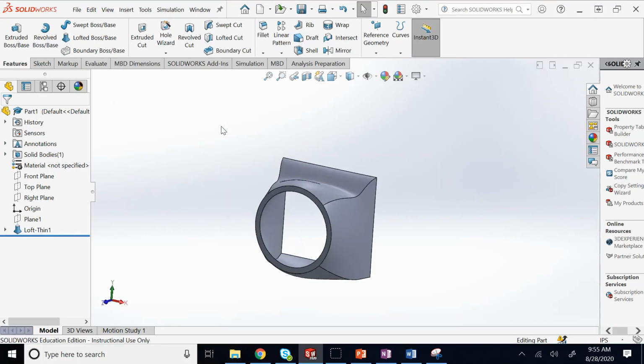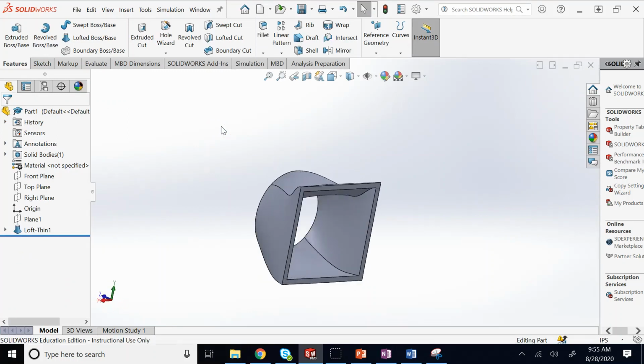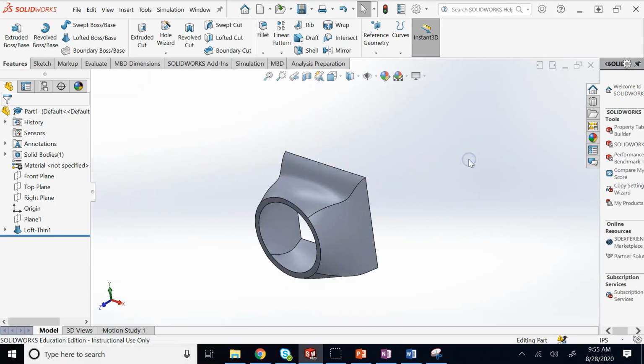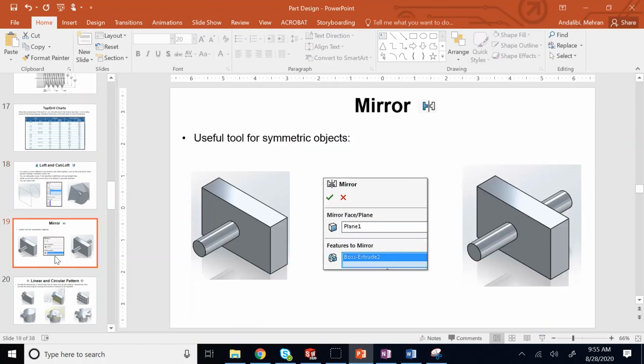Okay, very complicated. So loft, as I said, is the most powerful command, and it allows you to create very complicated objects. So just keep that in mind. And then you can do cut-lofts, right? So you can have 2 different profiles and cut a loft out of something. So it's exact same thing as this one, just hollow out the material.